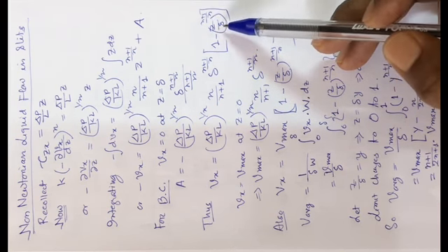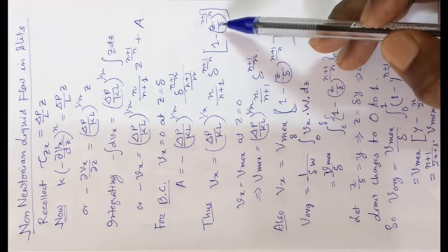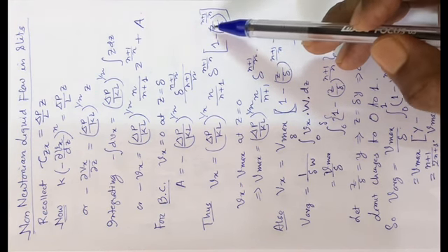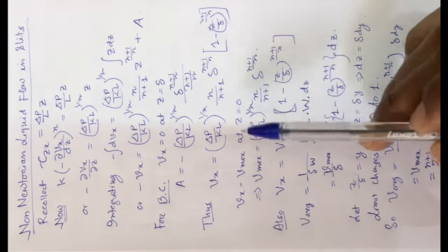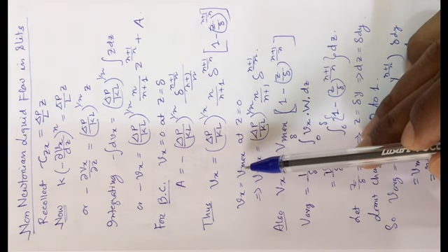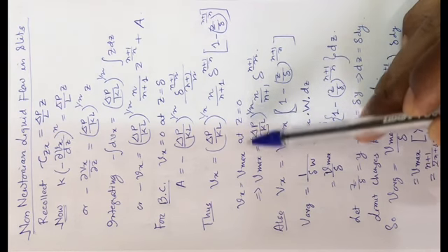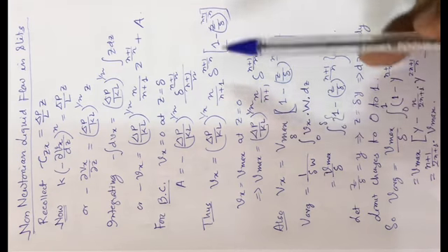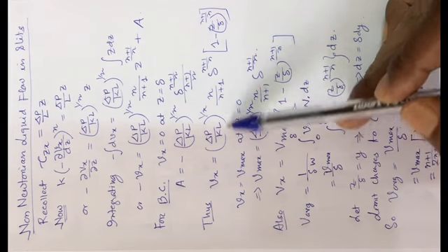So z by delta, you can call it the relative position. Okay, so the maximum value can be delta and the minimum value can be 0. In between, the z value will be varying. Okay, now velocity is maximum at the central axis location. Okay, meaning when z is equal to 0, velocity is maximum. Therefore, when we substitute z is equal to 0 in this expression, we get this maximum velocity. So maximum velocity is again this particular factor.